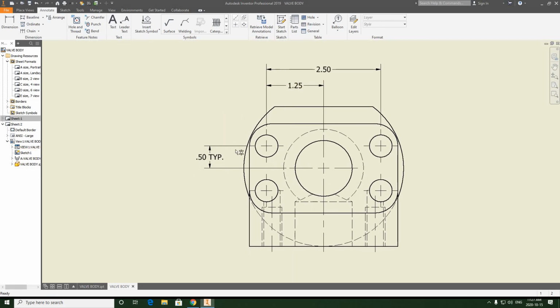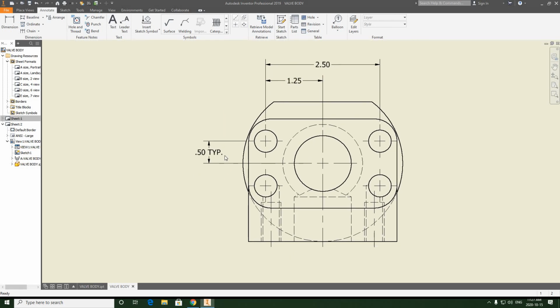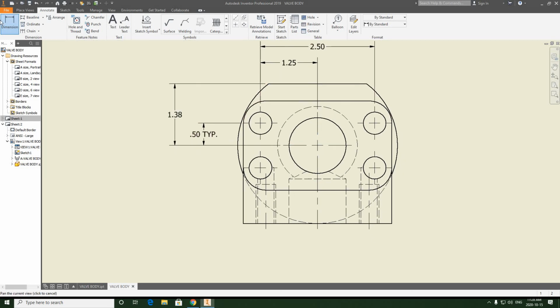I'm trying to use the tracking system when I place the dimensions to make sure that this looks proper. Now, we need to know, and a lot of these dimensions are seen on the sheet. So I'm going to the center line here, and I'm coming out to here, right? We're trying to keep the spacing looking nice and consistent.